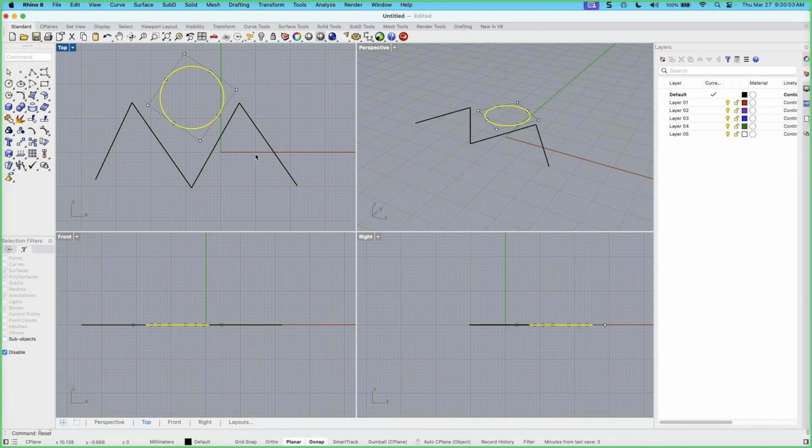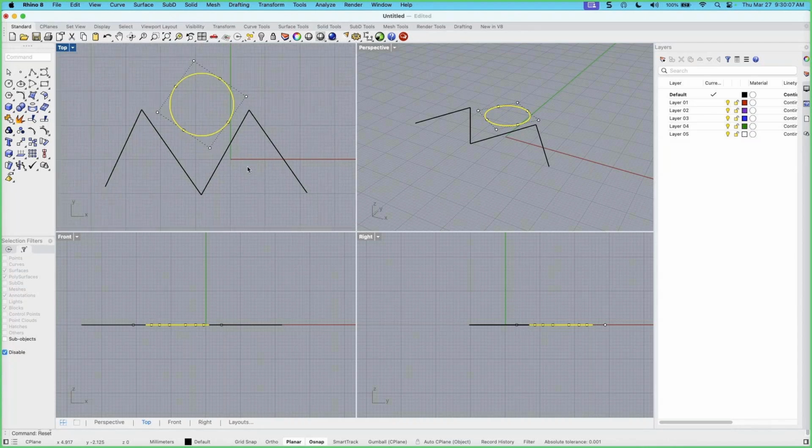And there are a lot out there, hundreds, thousands. So sometimes you just need to start clean and add the Grasshopper plugins back one at a time, and then figure out which one is messing Rhino up.